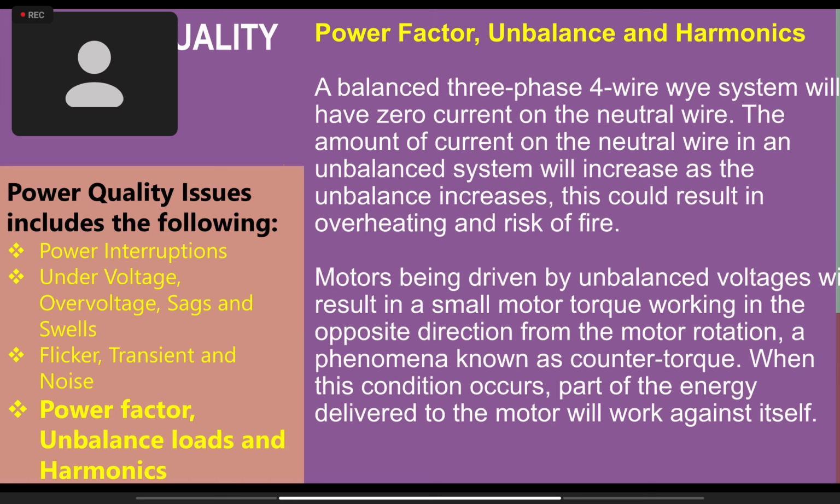And also to limit the difference in voltages for the three phases to less than 5%. Kasi if it's more than 5%, it will lead to overheating also to rotating equipments. Motors being driven by unbalanced voltages will result in small motor torque working in the opposite direction. So yung effect ng unbalanced voltage, may magkaroon ng heating because of the small amount of torque working in opposite to the direction of the main torque. So in the opposite direction from the motor rotation, phenomenon known as the counter torque. So in this condition, of course, part of the energy delivered to the motor will work against itself. So this will lead to the poor performance of our electric motor.